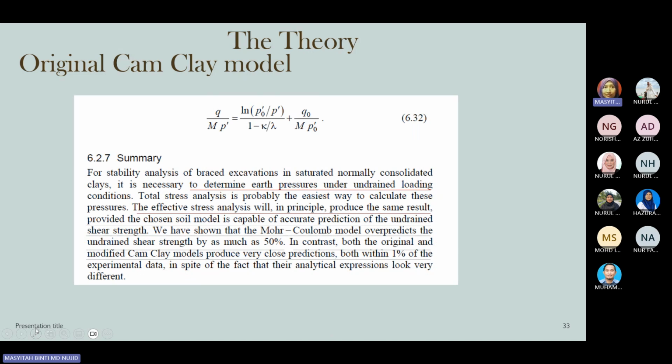So in summary, it is necessary to determine earth pressure under undrained loading conditions because this is very critical for the stability of the soil during the time of construction. So the total stress analysis is probably the easier way to calculate this pressure. The effective stress analysis in principle produces the same result, provided the chosen soil model is capable of accurate predictions of the undrained shear strength.